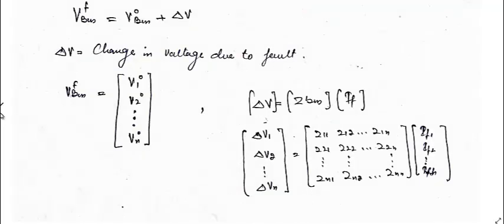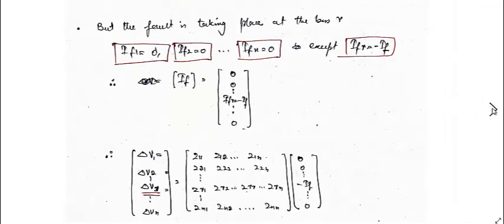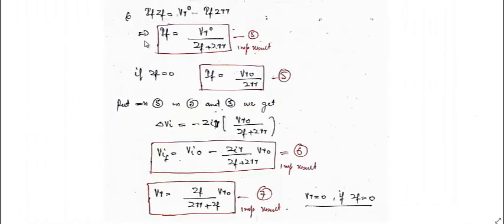So you can see it over here. This is the Thevenin circuit which we have already calculated. The total impedance seen by this, let us say only we have these 3 generators and we don't have any other, and the fault takes place at the bus where these generators are connected. So the total impedance seen by this point will be the parallel combination of these, this and this, if they are connected to the same bus. So this is the case when ZF is equal to 0.